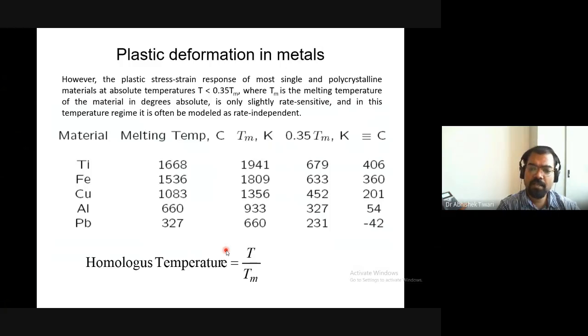Apart from that, if the dislocations, during their movement, are getting locked, for example at inclusions or semi-coherent interfaces or incoherent interfaces, or at dispersoids, as we have discussed in dispersion hardening, it can also happen that they get locked at Lomer-Cottrell barriers. It is easier for dislocations to cross these barriers as you increase the temperature, because dislocations can climb.